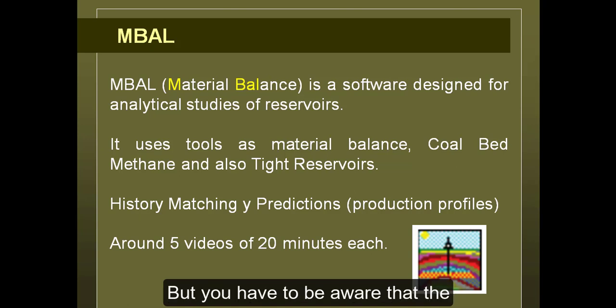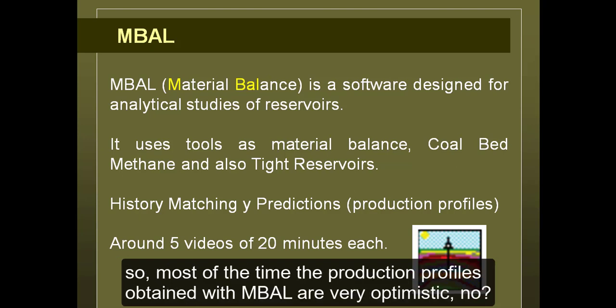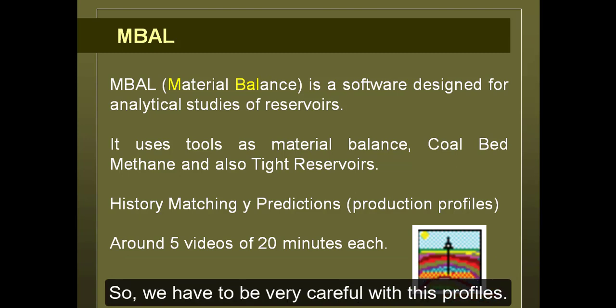But you have to be aware that the production profiles obtained with MBAL don't consider the bottlenecks of surface facilities. So most of the time, the production profiles obtained with MBAL are very optimistic. So we have to be very careful with these profiles.